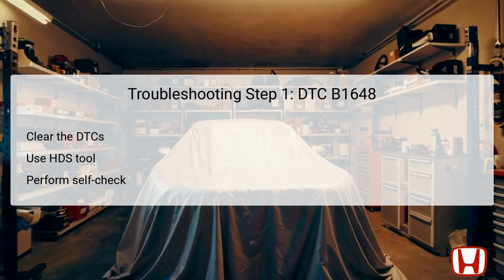If DTC B1648 is indicated, this confirms that the circuit issue is ongoing, and you would need to proceed to the next diagnostic step. If no DTC is shown, the vehicle may be experiencing intermittent failure, and checking for loose or poor connections would be warranted.